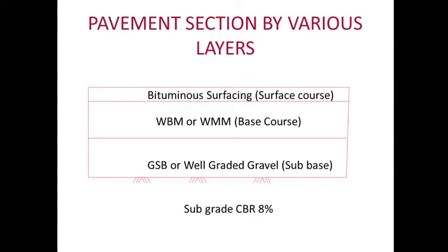The base, which comes immediately next below, is the medium through which the stresses imposed are distributed evenly. Further distribution of load is also provided by the subbase layer. And subgrade is the compacted natural earth immediately below the pavement layers. The top of the subgrade is also known as formation level.